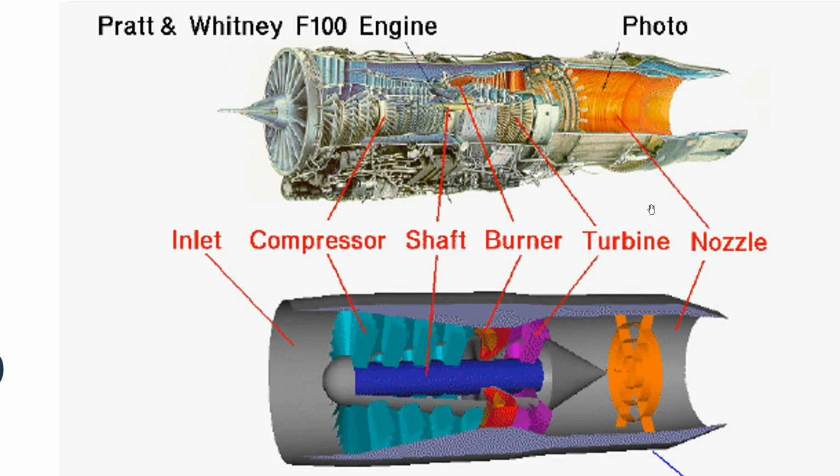The thrust generated by the engine can be further increased by incorporating an afterburner, also known as reheat, into the engine design. This system injects additional fuel into the exhaust stream downstream of the turbine, where it is ignited to produce extra thrust when required.